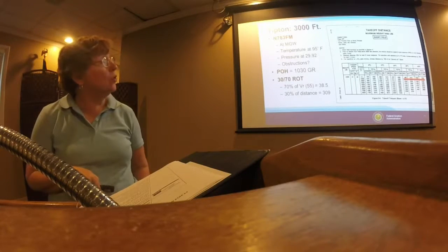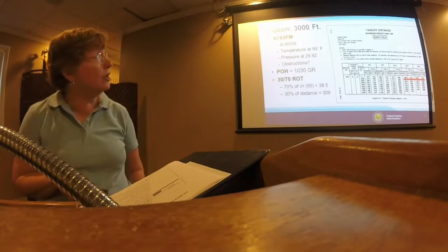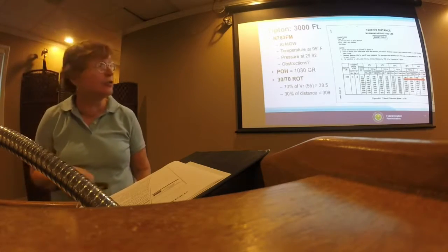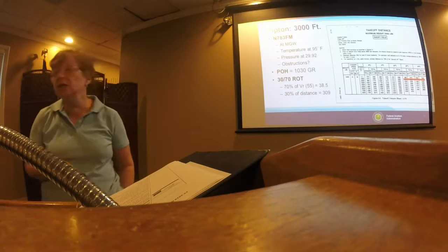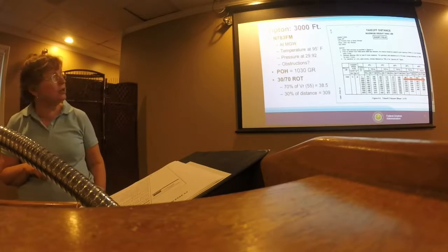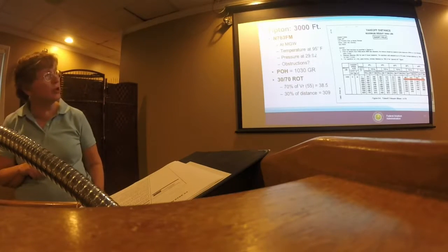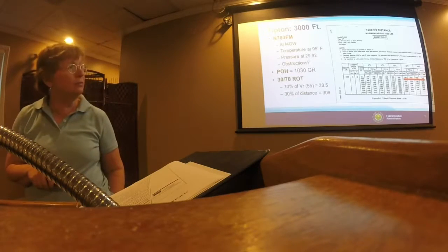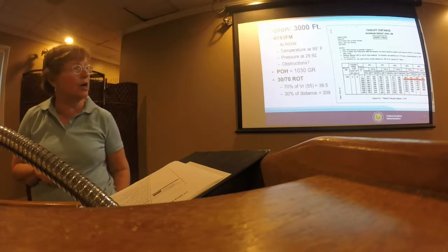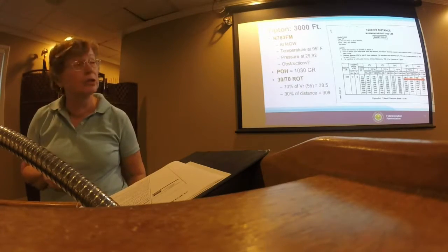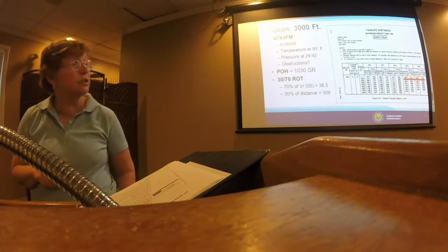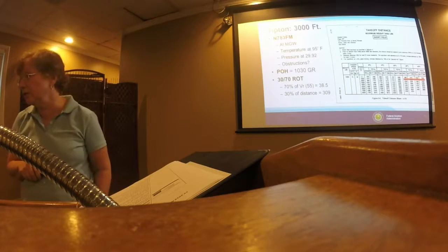So for Tipton, I went ahead and looked at the performance figures for 783 Foxtrot Mike, making it easy on myself. I also made it a standard pressure, so I didn't have to calculate that as well. If you're looking at the takeoff distances, we're talking about 995 for 30 degrees Celsius and 1066, I think it is, for 40 degrees Celsius.